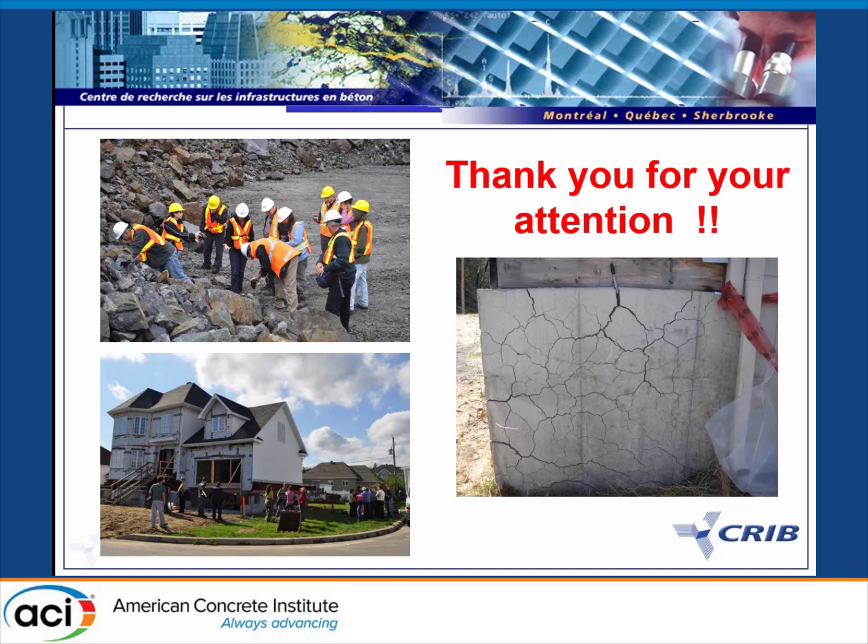When you find your ettringite and thaumasite, are you finding it within the paste or in voids, and at what magnitude? You didn't have a magnification or a scale bar. Where is it from? They are in the paste, in the reaction rim around the aggregate. And it's a mixture. We are not sure if it's a mixture of ettringite and thaumasite, but we think it's a solid solution between the two. Are you finding that at 5,000x, 10,000x? I should ask Andreia.